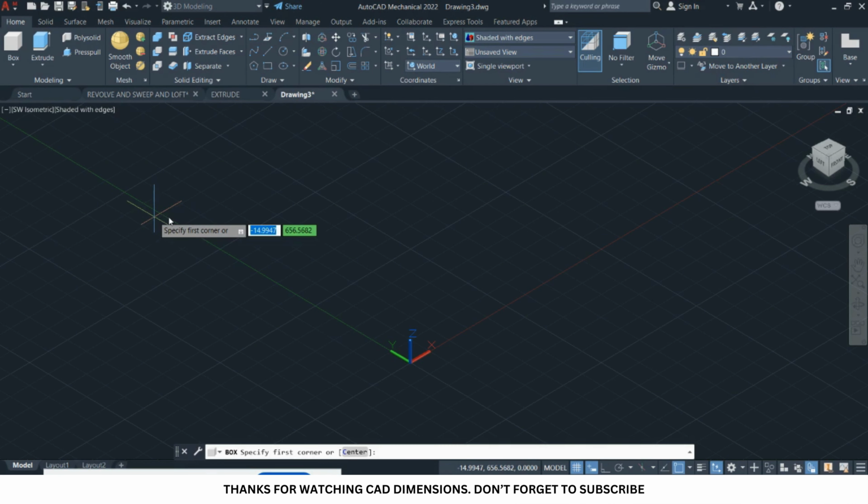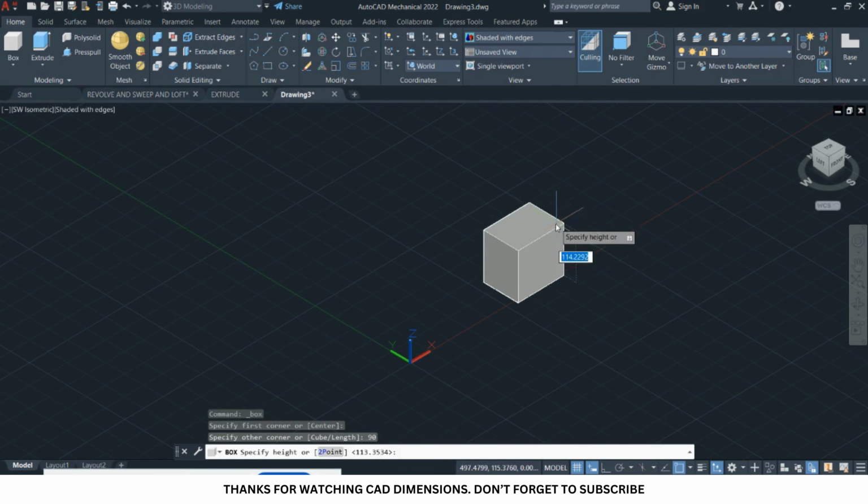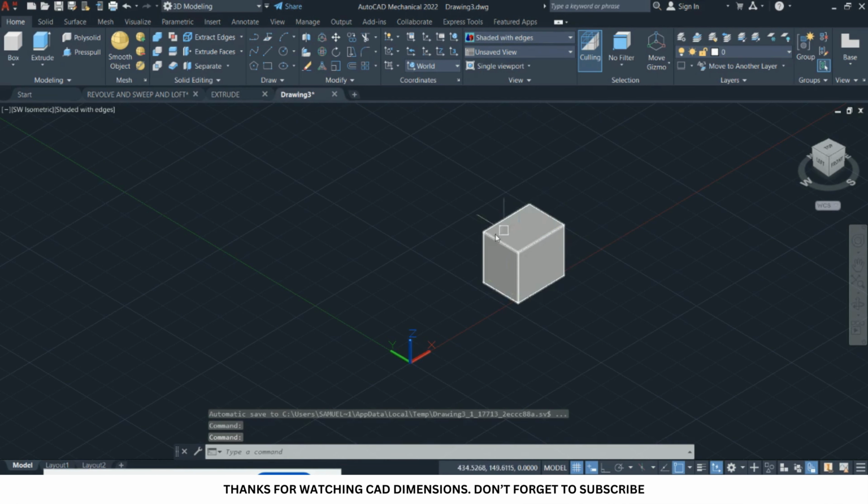All right, so if I select the box, I just have to come to the working space. I specify my first point, click, and then if you have your dynamic input activated, you will see the indicator telling you to enter the dimension for the box. For this one, maybe I want 120. I press the tab on the keyboard, I enter 90, then press enter finally. Then the height of my box, I can specify maybe 110, and I've been able to draw a box without going through the 2D, then switching to 3D.